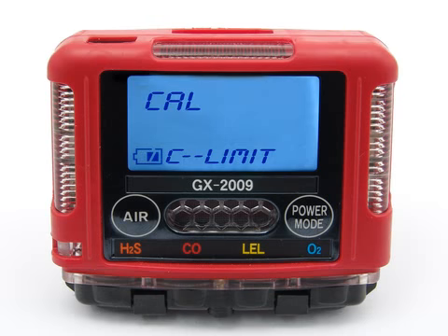If Cal Limit display function is turned on, the screen that appears next depends on how Cal Limit check is set. If the unit is due for calibration and the Cal Limit check is set for Confirm to Use, then the Cal Limit prompt will display and the alarm LEDs and buzzer will pulse several times. When this occurs, press and release the power mode button. You will hear a beep and the startup sequence will continue.